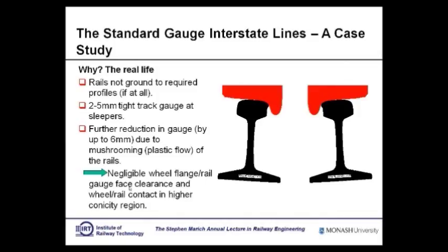So usually railways order their sleepers with a tight gauge. But when they place the rails on the sleepers that have a tight gauge, and the rails actually have these bulges, which tighten the gauge even more, you've got no gauge left. Or you have very little gauge left. And of course, under those conditions, if you have a worn profile, the worn profile will ride on that point, which is a no-no, because as I showed in my second or third slide, that's the point of very high effective conicity and very high rolling radius differential. It all makes sense, doesn't it? Okay. So that's a real problem.